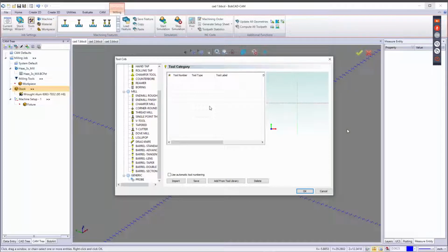It may not pick the right tool up. All you have to do is click on the tool crib up in the top left of the tool page and get the right tool in there. By default, I think it looks at a half inch tool if you don't pick something else out from the ML Rough when doing a pocket or profiling operation. And that's from the system library.